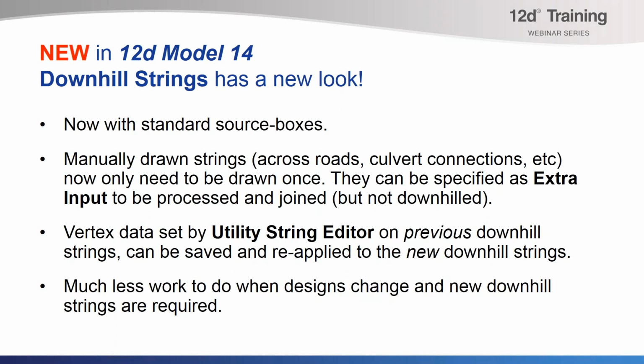Of course, this option simply requires superstrings as inputs that have Z values. It doesn't really have anything to do with drainage strings, and in fact it's not tied to the water modules or anything like that. It just comes with the base module, and you simply require superstrings with Z values, and that just happens to be what most civil designers will provide you in terms of the strings that they create when they run their apply MTF functions and things like that.